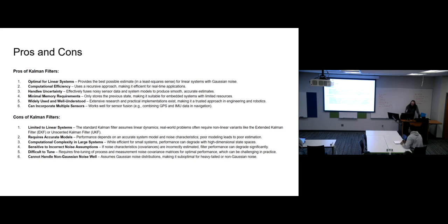So your model becomes more complicated, but because of that, you can capture the rich dynamics that show up when you actually take Jacobians and take derivatives. But taking the Jacobian of like an F-22 is something no one is probably capable of doing, at least not in this room. It requires an accurate model. No matter what Kalman filter you use, this is all based on your model. If you can't model your sensor well and know how it's going to break down, how I'm moving in some form, if you're making guesses, a particle filter does that better.